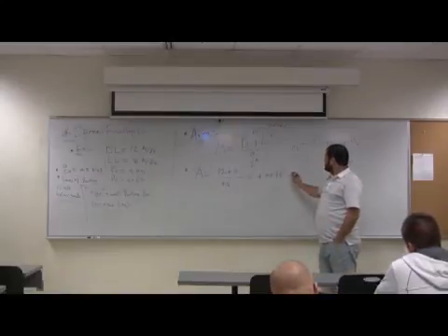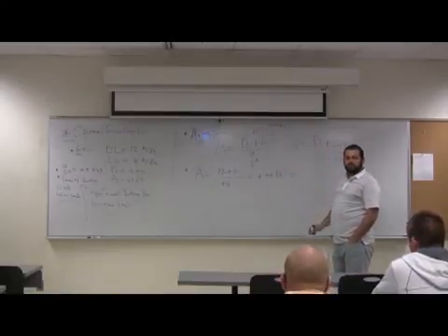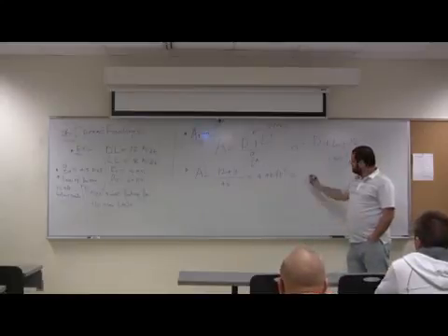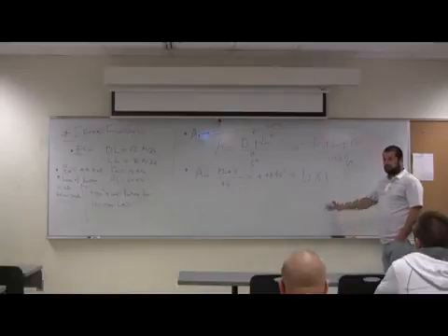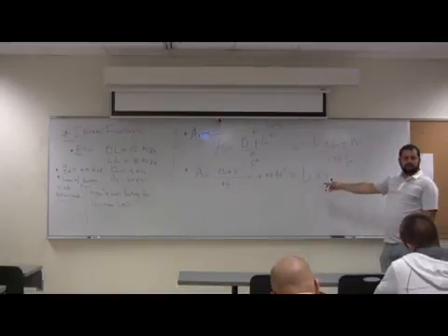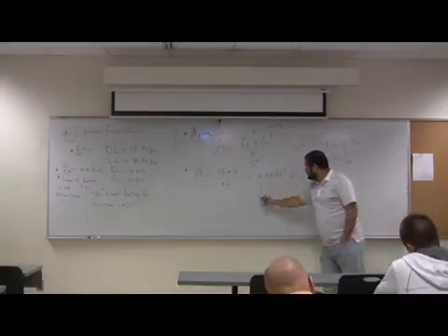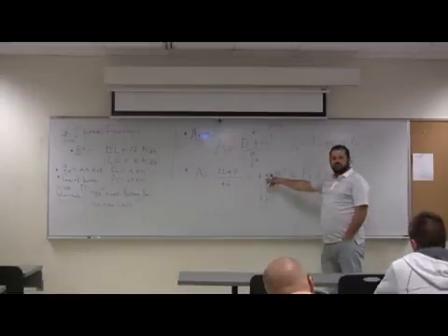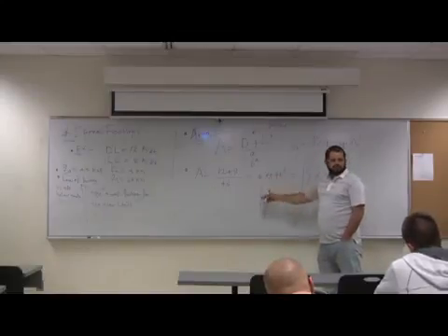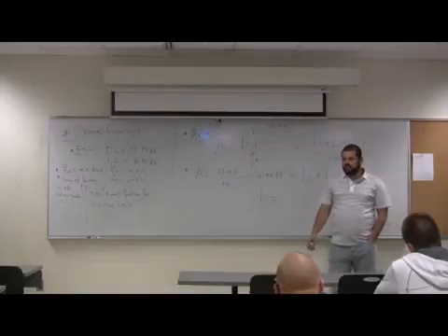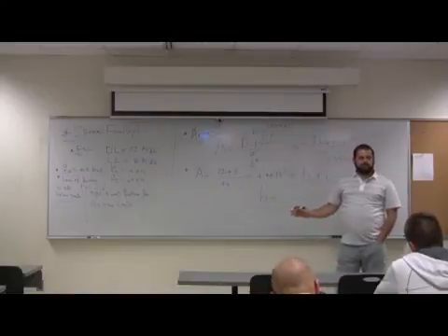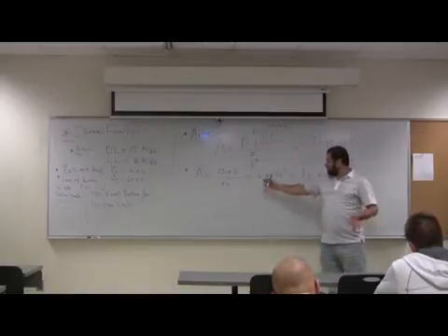What's this area equal for the wall footing? That's per foot. B times 1. So this is B times 1. So what's B? Required B is 4.44. How much do you want to go with? 4.5? Absolutely fine. If you went with 4.5, absolutely correct.